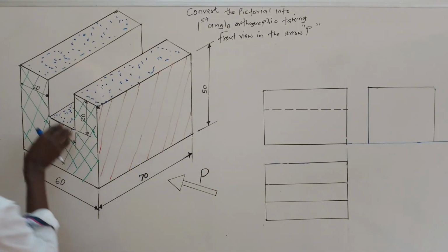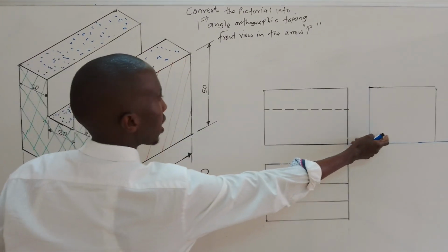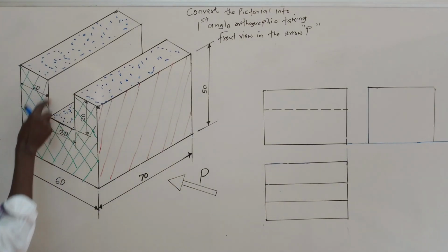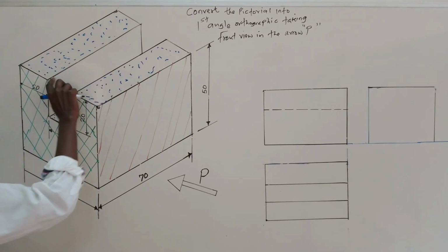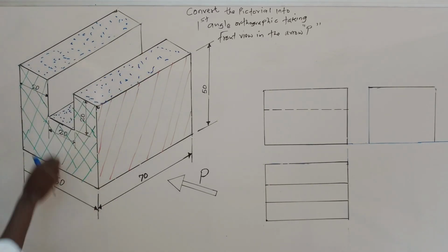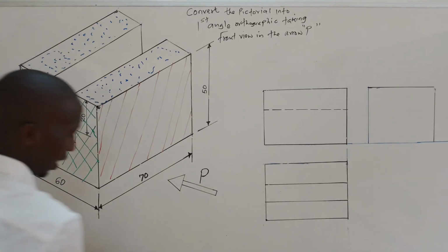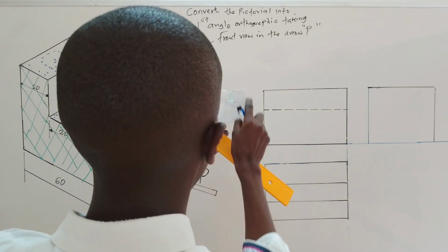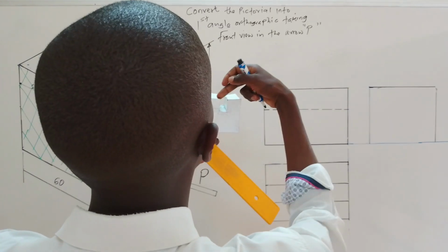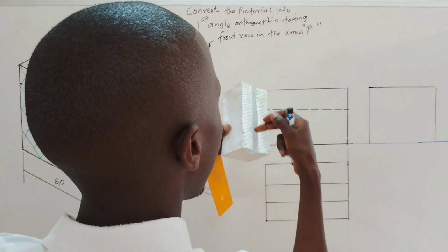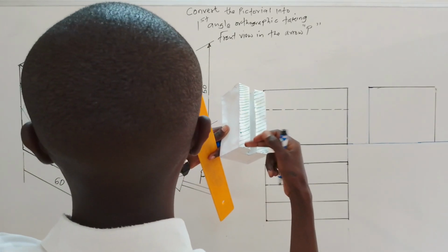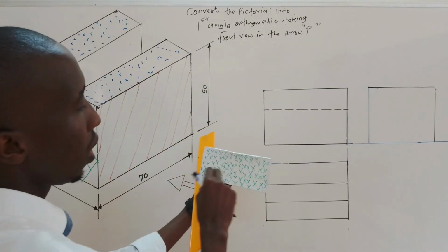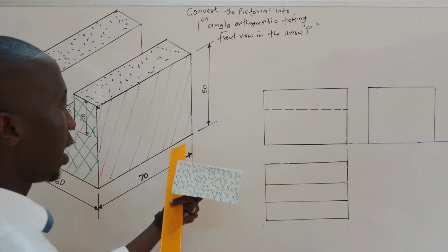So we have, assuming that we don't have this, so we've got our drawing. Now we want to cut this surface, this one. So remember, we shall not see any line. These lines going this way are not visible because they are inside a corner. As you look this way, we are just able to see these lines, but not this span. This span is not visible. The only place you will see this length is on the plan and maybe on the front elevation.